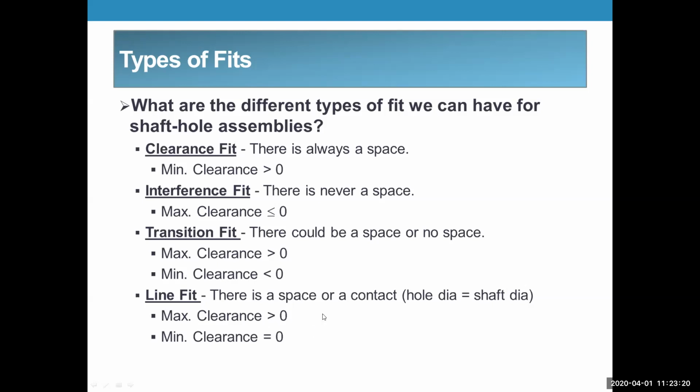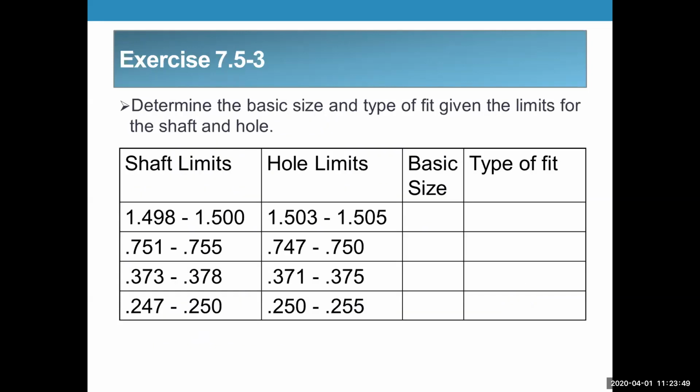Well, the way I look at it, if you have clearance, if the shaft will go into the hole, even though they measure the same size, they're not really the same size. There's a few ten-thousandths or hundred-thousandths or microns difference that you can't measure that allows them to fit together. Because if they're truly line to line, it should be an interference fit. That's my opinion.